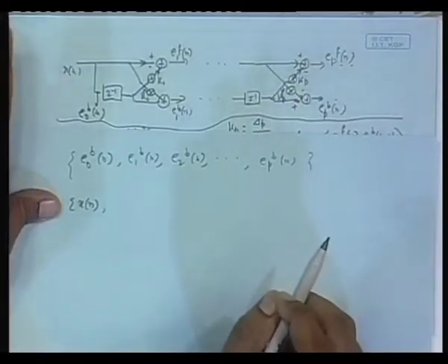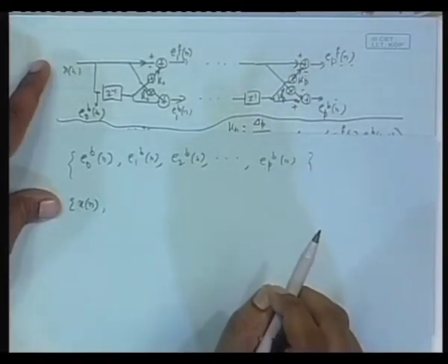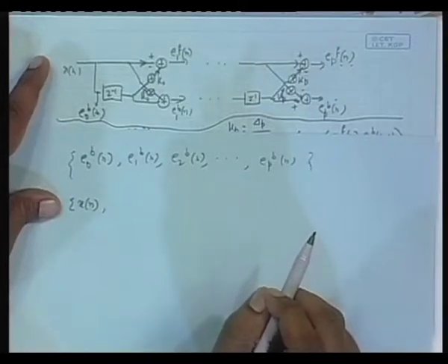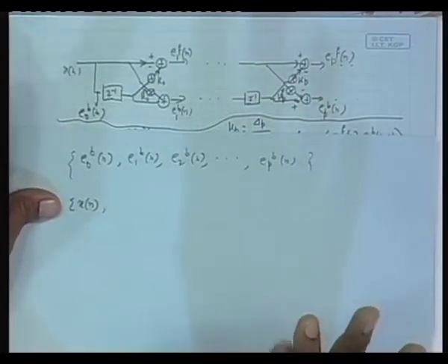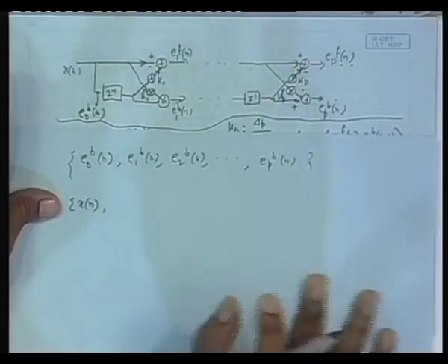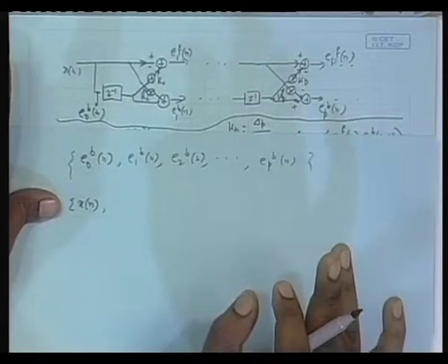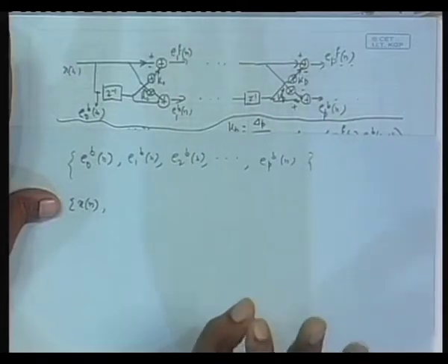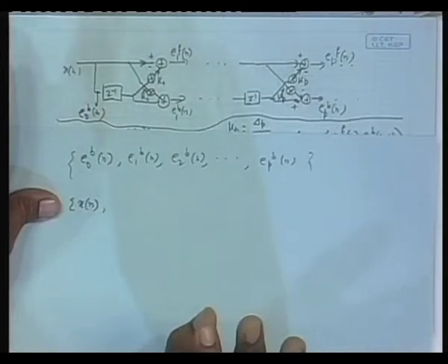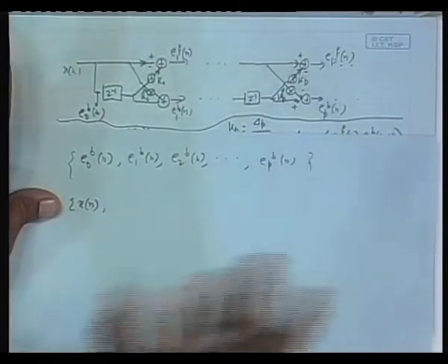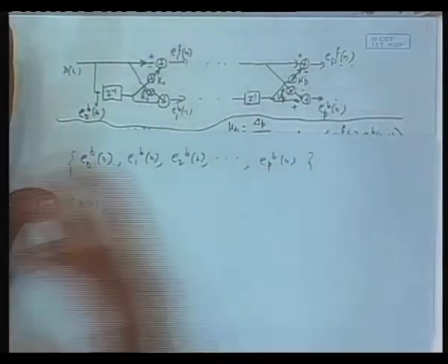Suppose there you got pth order filter, I say that you get me the p plus 1th order filter. Again you have to compute R inverse p. From the pth order filter coefficients, you cannot get the p plus 1th order coefficients directly. But R inverse p formula, you remember optimal filter, pth order filter you know, okay, orthogonal projection, these are the projection coefficients or filter coefficients, this is the formula R inverse P. Get me same for P plus 1, okay. Again another R inverse, another P, bigger size. That is what we had there.